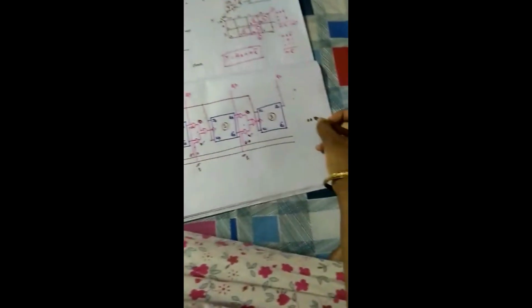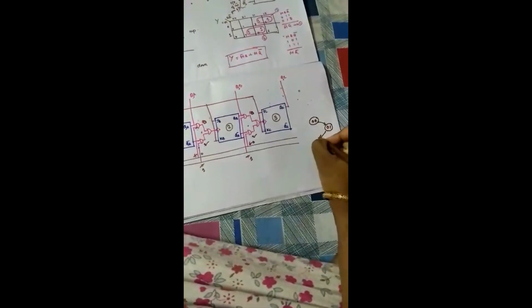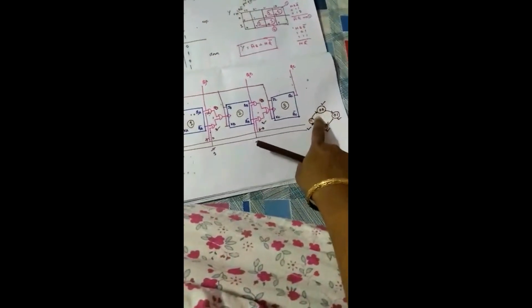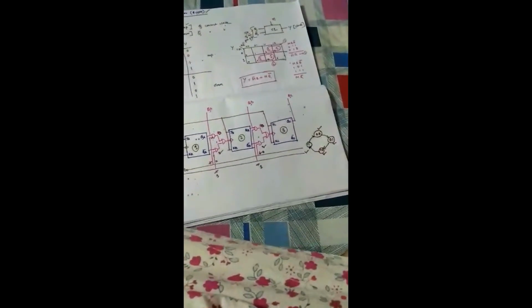Now in the previous video I forgot to explain the states. Whenever any counter is changing its state from 0 0 to 0 1, then 1 0 and then 1 1, say it is counting from 0 to 3, then each of 00, 01, 10 and 11 is considered a state. This is called the state. This will become clearer when we discuss counter design. So up to the up and down counter, that means the universal counter.